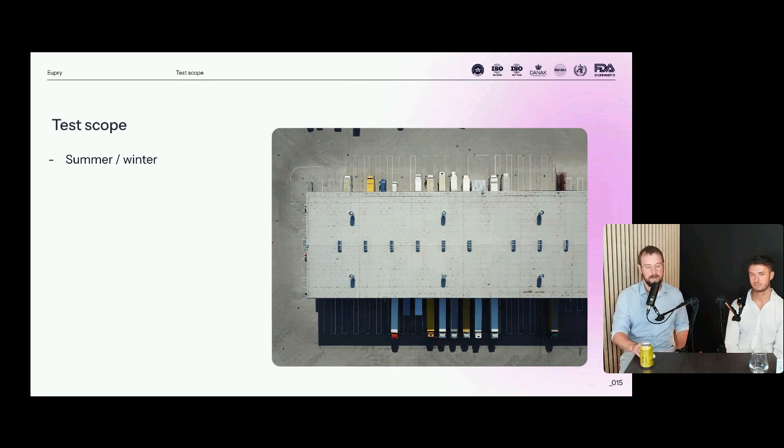So that is clearly one of the things you need to consider. And for buildings that are temperature controlled but also facing the outside environment, I have yet to see the rationale that justifies that you don't need to perform summer and winter mapping. So in most cases, the answer is yes, you do need to perform summer and winter mappings.